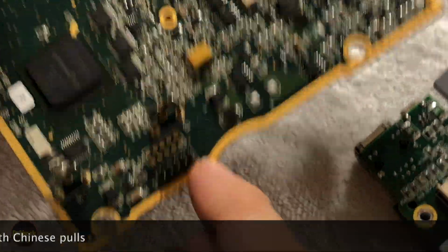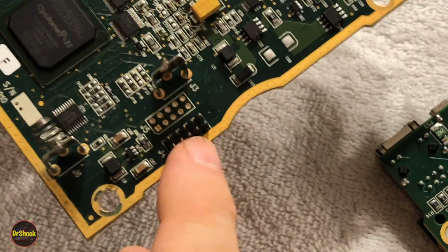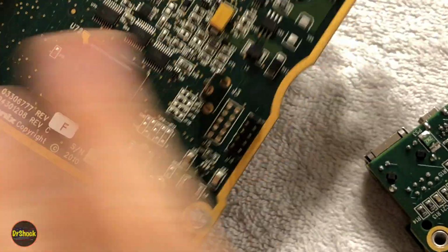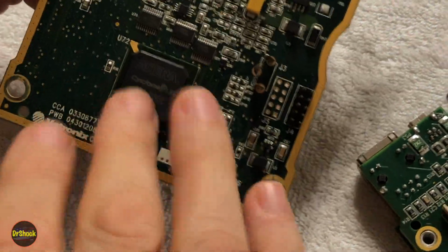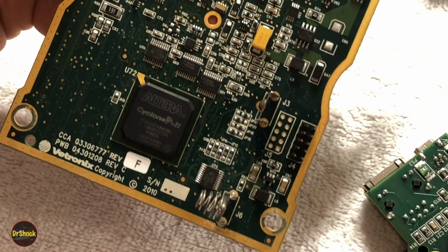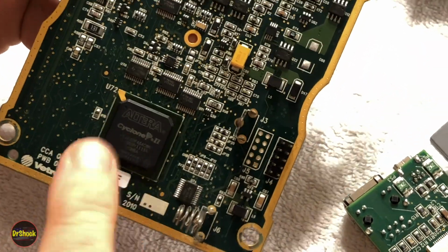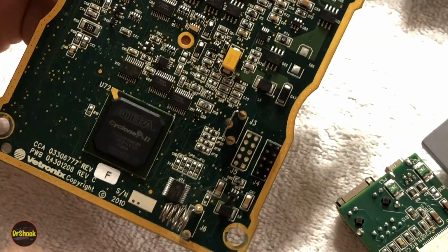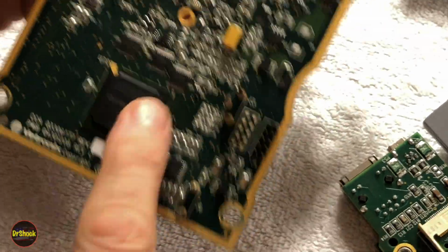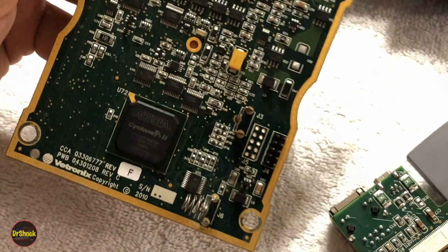These are those pins I was talking about earlier, right? And I suspect these are the pins that the factory would use to program this device. I don't know if you put a blank one on here, if when you go through the recovery process, it would be able to program one that's blank. Because besides the actual programming of the protocols that are in here, there's probably a configuration that's done one time, and that may need to be present in order to do the update. You don't know. So you might end up making this even worse by trying to repair it. But we'll give it a shot and see if it is something as simple as a broken solder ball. I seriously doubt it, though, but it's worth a shot.